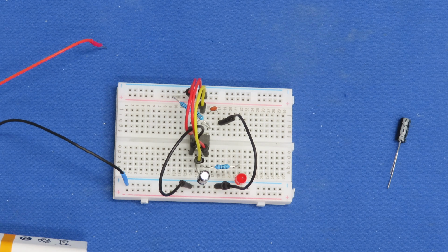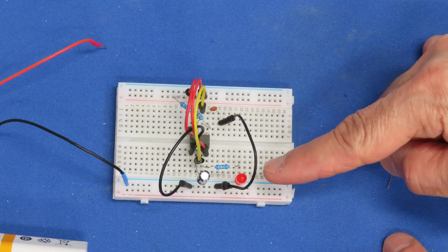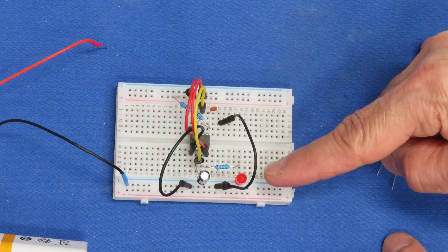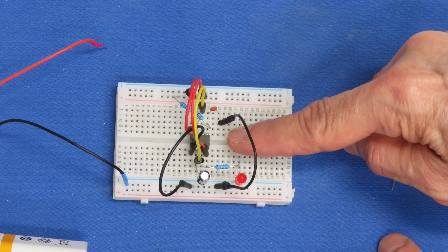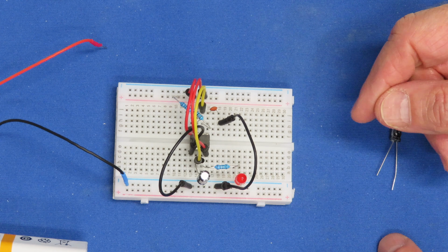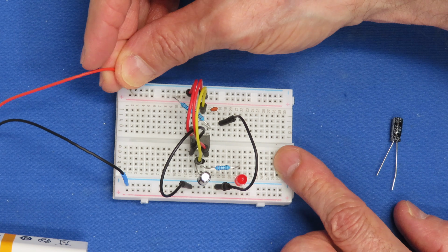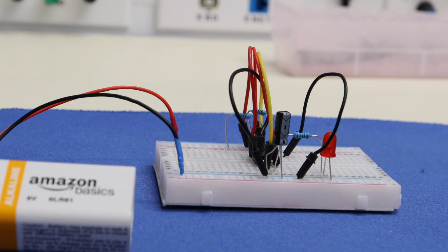And so here's our astable 555 timer demonstration on a solderless breadboard, and you can see my LED over here, which is the output of it, and buried within these wires down here you can see the 555 timer. Now I'm powering this with a 9-volt battery, and so I'm going to connect the battery's positive to get everything going. And you can see the results right here. The LED is flashing roughly once per second.